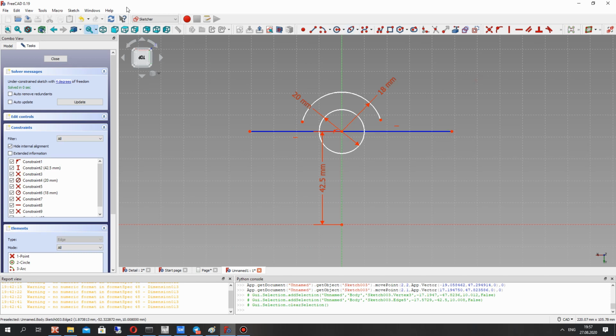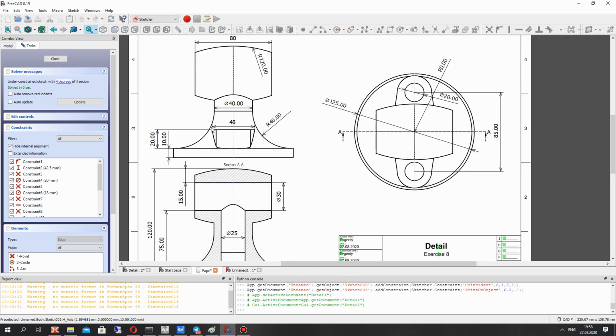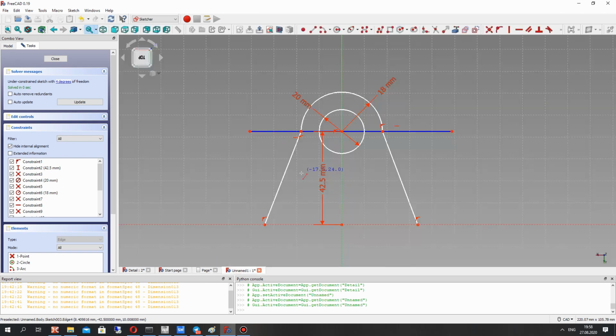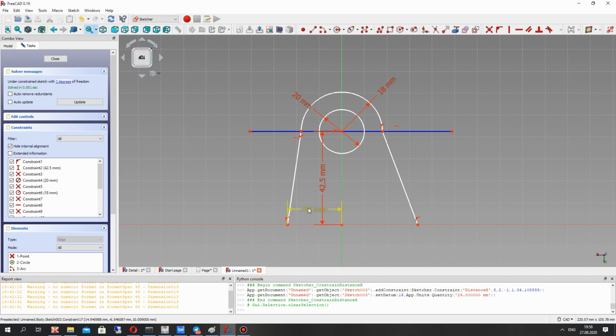These blue lines are used as help for the creation of different things, but they are not used for the creation of the sketch. They just help to create the lines on the sketch. Okay, let's set this central dimension, 24 millimeters for both.